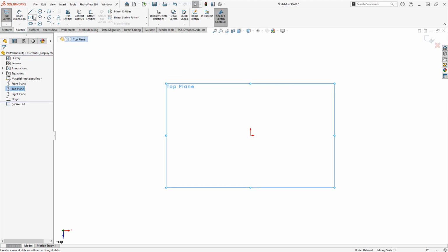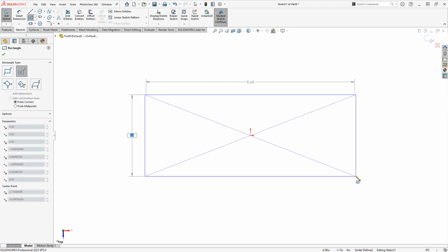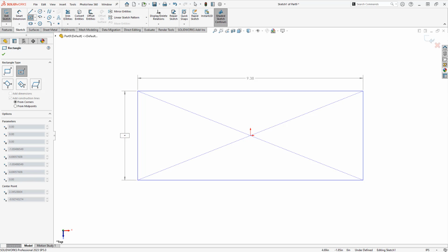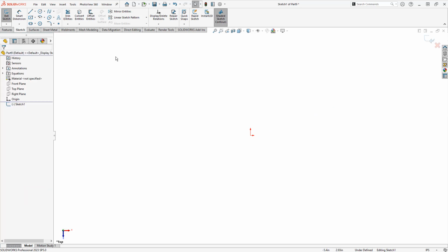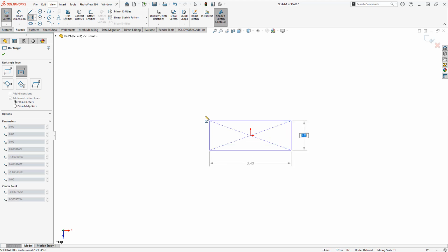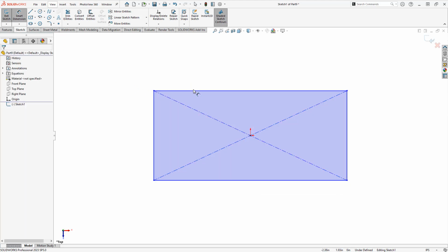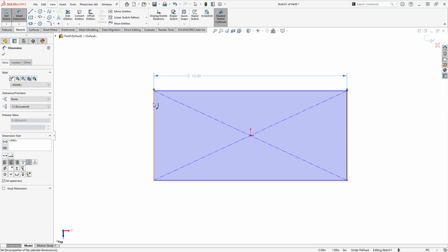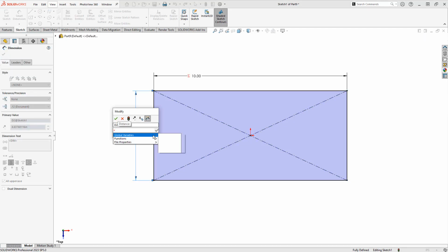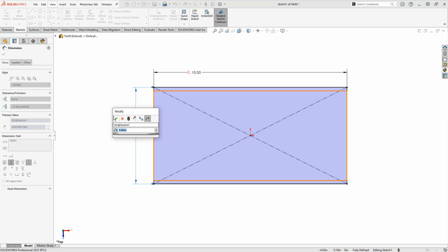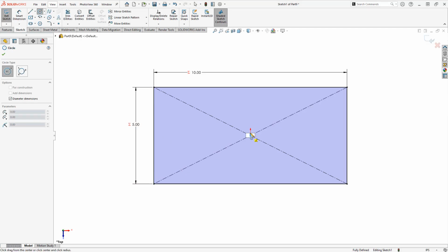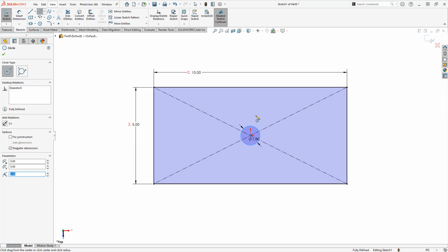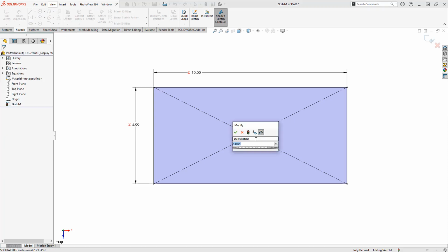So we'll start a new sketch, center point rectangle just like before, but this time if I hit equals in the dimension dialog, it's going to open up my global variables for me to simply select things like length. We'll do it here, hit the equal key, global variable width, and we'll add that center diameter circle here. I'm going to have to give it a value and edit this. We'll hit equals and we'll give this a hole diameter value.